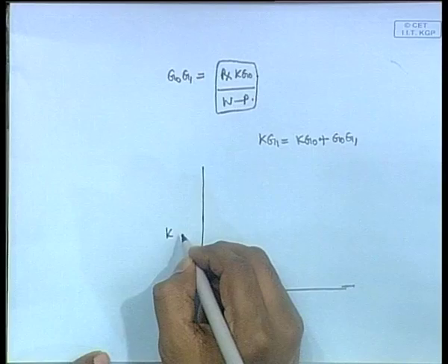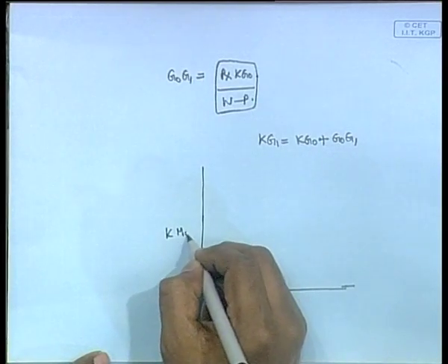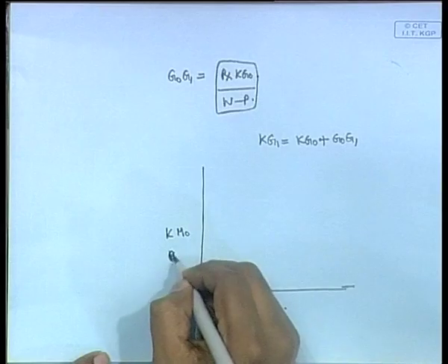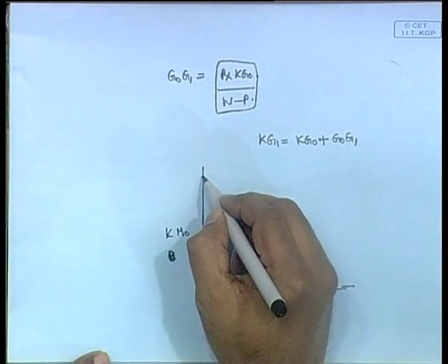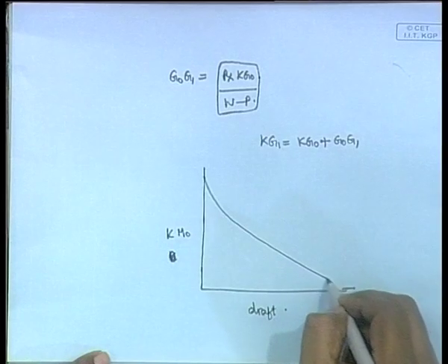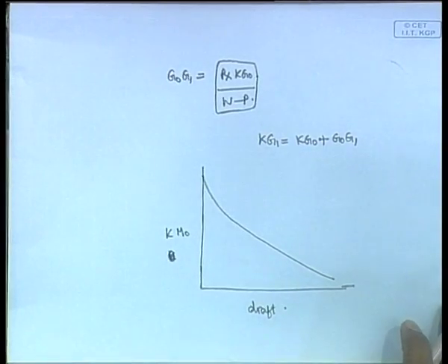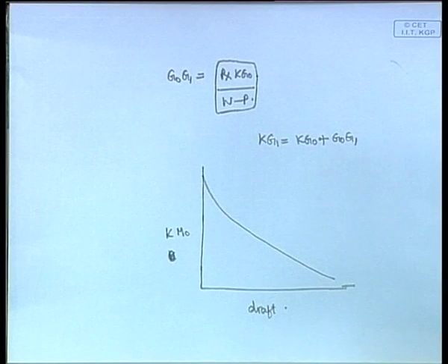So km0, or all these values km0, actually comes down like this. So, this should be km, not km0. No, it is km0, that is a good point, but it is km0 because m0 means when the ship is in an upright condition. Ship can be in an upright condition at different drafts, but in the upright condition. That is the meaning of 0.